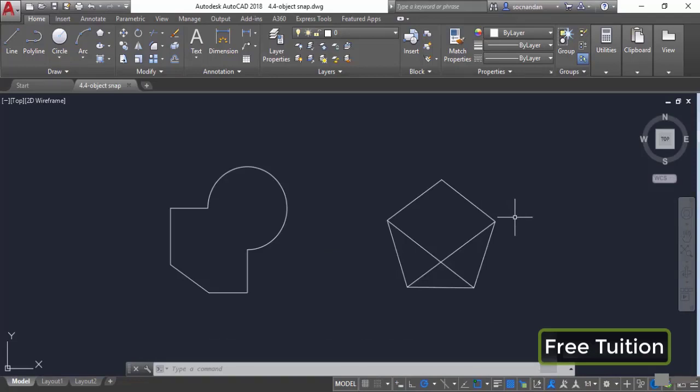In this video, I will tell you about simple object snap tools. The object snap option comes into picture when you want to make geometries with respect to the existing geometries or their points. For example, here we have these geometries, and now I'll select the line tool, and let's say that I want to start this line from this endpoint somewhere here. When I move my cursor close to this endpoint, this small endpoint box will appear, and on the tooltip you'll see that its name appears as endpoint. Now even if I don't click on this exact endpoint, the cursor will still snap to that endpoint, and that's because we have this object snap option active.